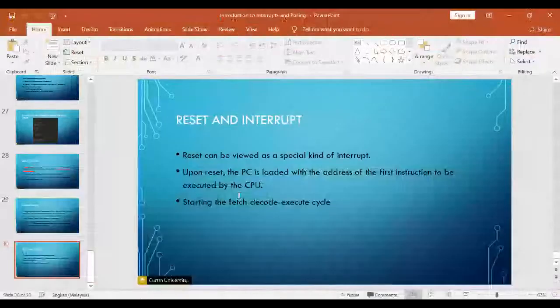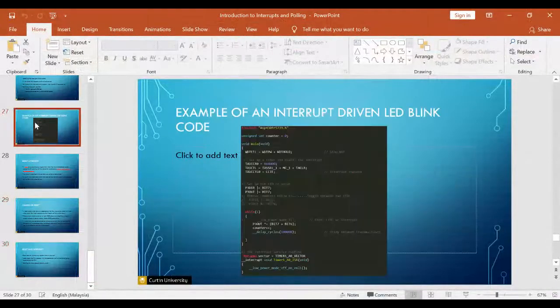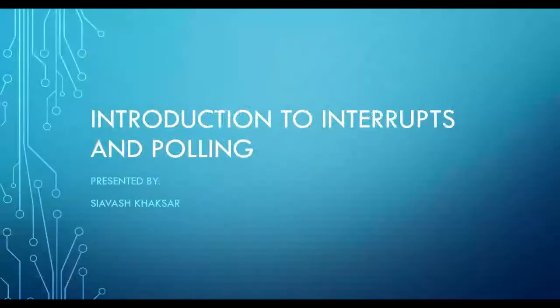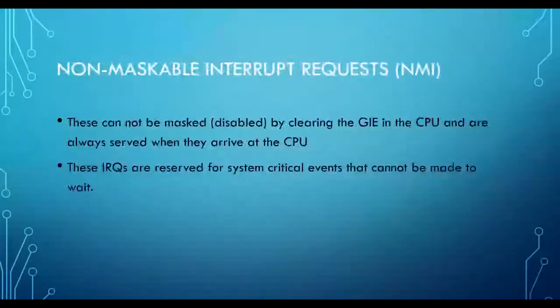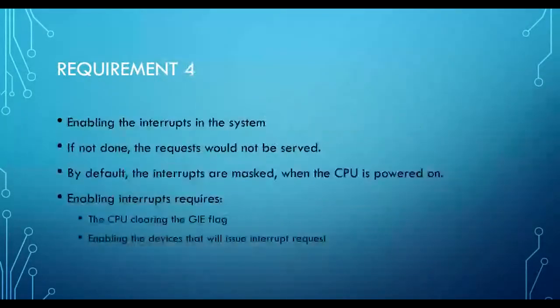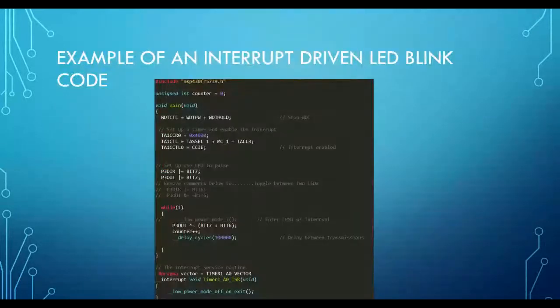This is a template. Look at this. We're not going so deep into this, but the template probably looks like this. You have your main code, so do something in main, and then you will define your interrupt. This pragma vector defines what triggers the ISR.